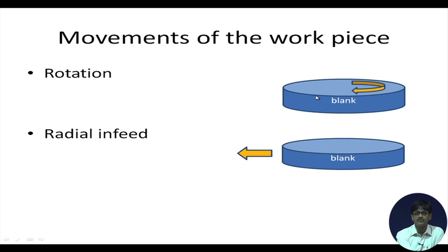The workpiece is also rotating, because we are creating a condition of rotation of the cutter and the blank together. So, this motion has to be provided as well, and the workpiece has radial infeed, which we noticed during the simulation.